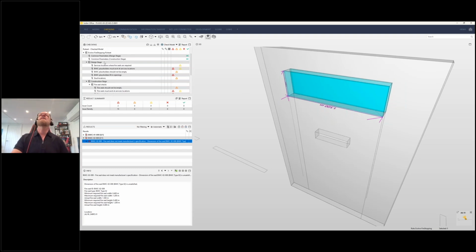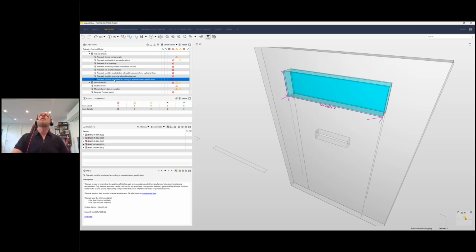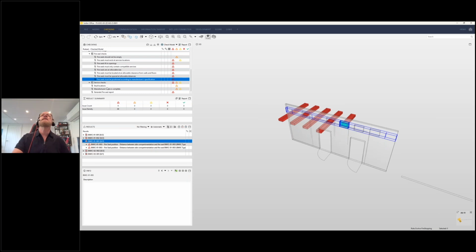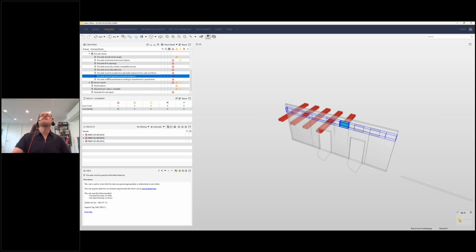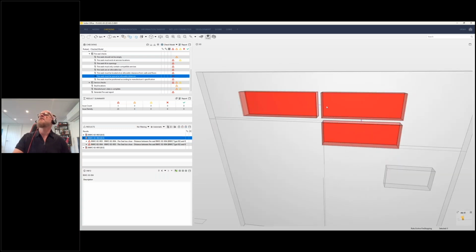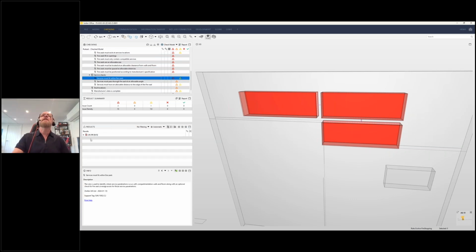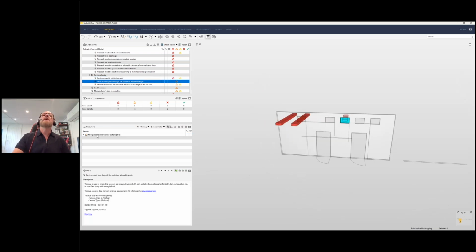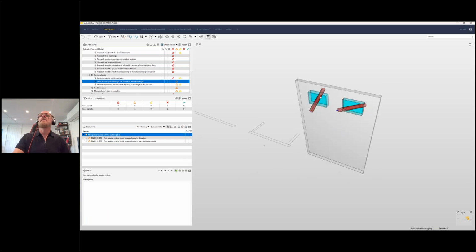All that information is coming back from the common parameters and the spreadsheet. It will look at whether things are positioned according to the manufacturer's specifications, whether the fire seals have actually got correct spacing. So again, are they constructible? As you can see here, these are just too close. There's not enough wall material between to support them. We'll also do separate services checks to make sure that they fit within fire seals. Obviously that one's going to get picked up again there, that they're passing through at allowable angles to make sure that that's allowable from the services manufacturer.